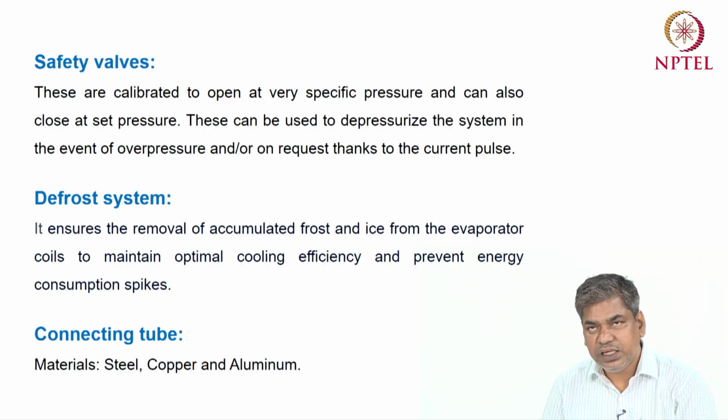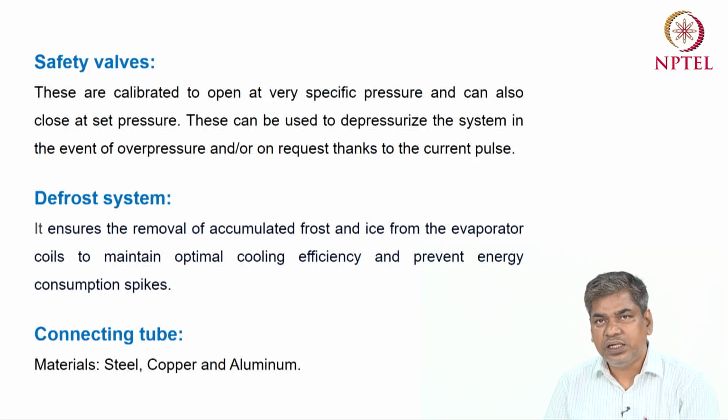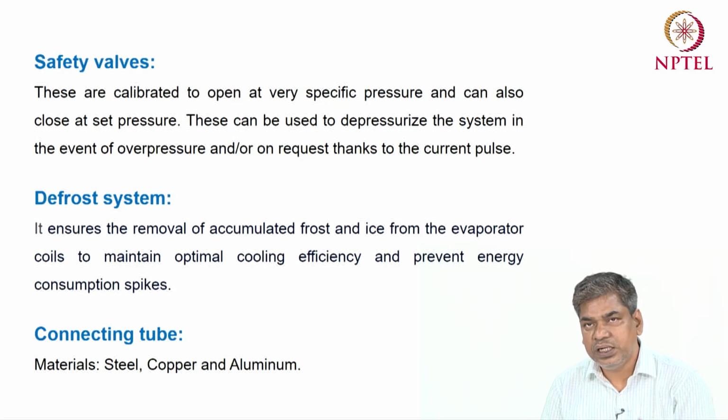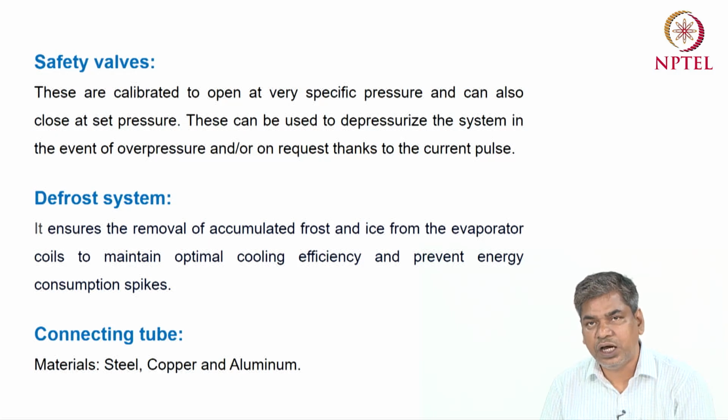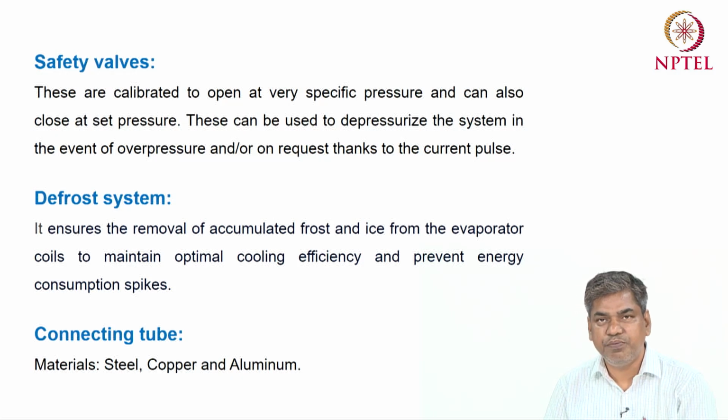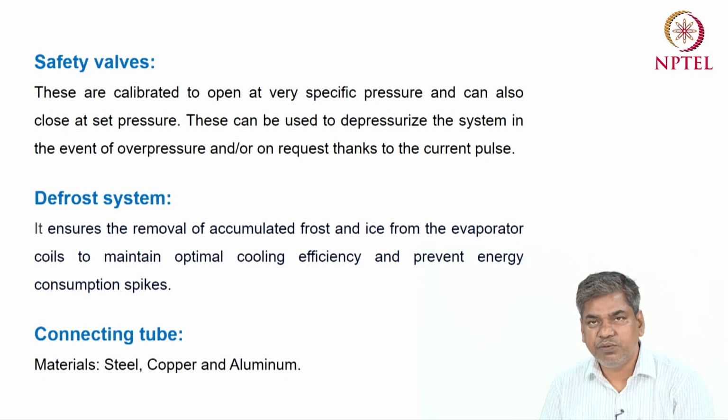Okay. Similarly, in the case of low pressure there is also a problem. If the pressure is very low, that means the system will be working at a negative pressure, and the evaporator temperature will also be reduced. In that case, there may be a chance of leakage from outside to inside, and outside air will come into the system, and the moisture that is there will form ice. So that type of problem will occur inside the system, which is also an undesirable condition.